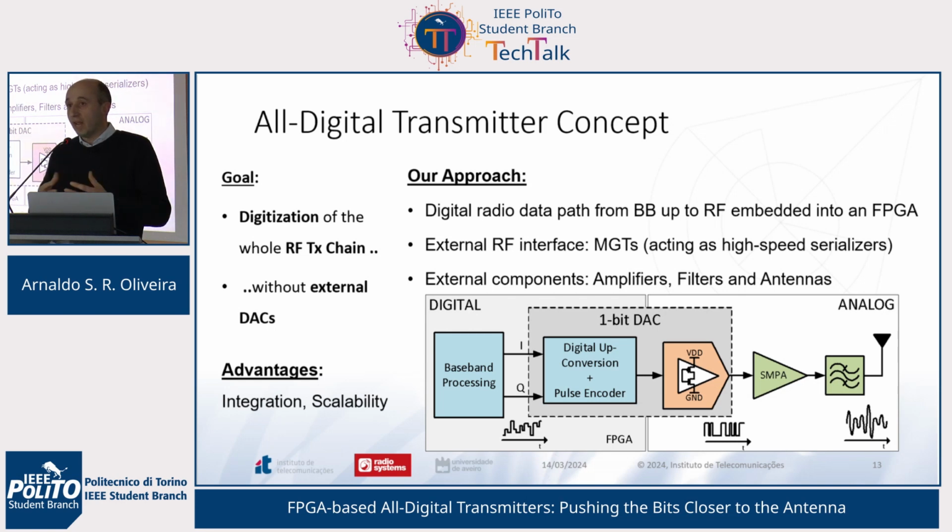So these are generic parameterizable transceivers that support the implementation of these high-speed serial interfaces, and in fact, to be honest, we are using them out of specifications. We are using them for an application that the manufacturer did not think about when it decided to integrate these blocks on the FPGA. But we found a different application for those transceivers.